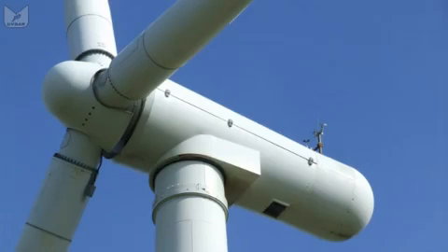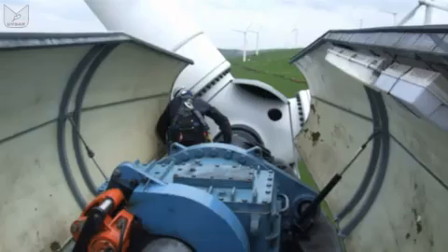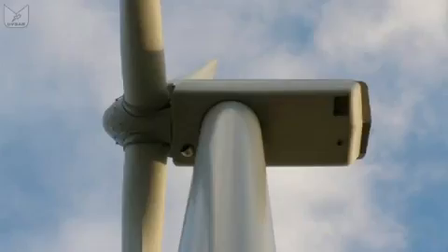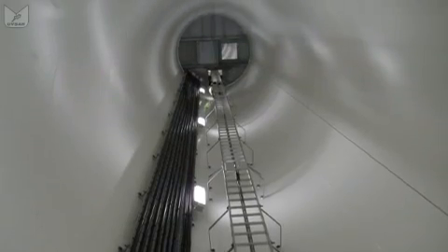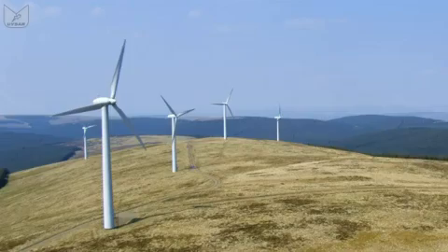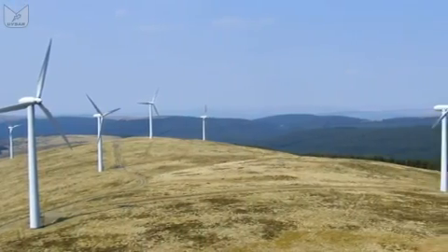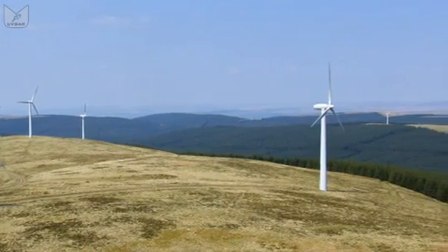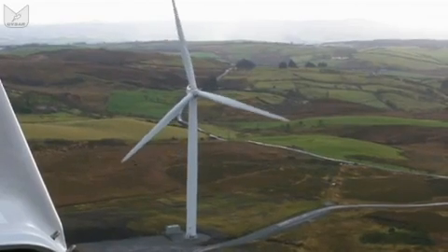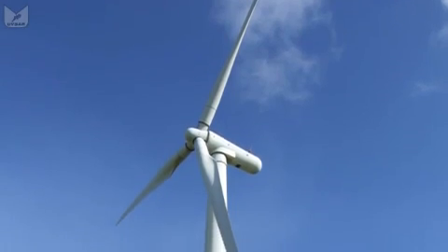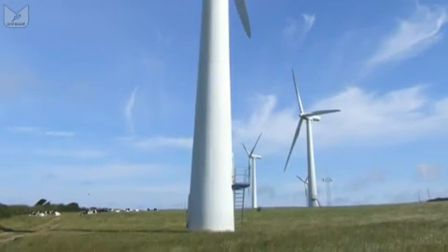And in this nacelle we have the generator, often a gearbox and occasionally a high voltage transformer, and the whole thing sits on top of a tower which is mostly there to keep the blades from digging a hole. We tend to class turbines by their power output and hence their physical size. Wind farms might use many sub-megawatt turbines, each producing 400-600 kilowatts each, or a few multi-megawatt turbines producing maybe up to 3 megawatts per unit. Apart from physical scale, they are arranged a bit differently, so let's start by looking at a typical sub-megawatt model.